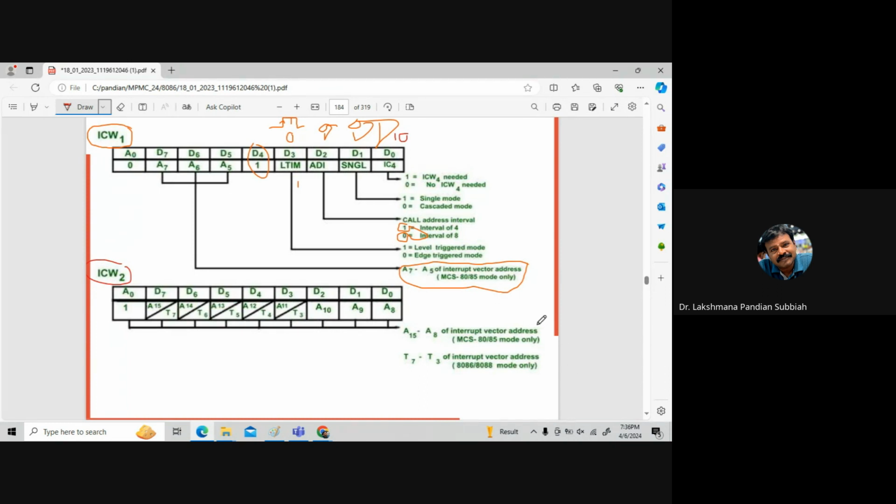So for which particular address are we going to have that interrupt vector content? Where is the interrupt vector? Where we have the corresponding address, we are going to have A15 to A8. So this is the address, and this is going to have the interrupt vector. In the interrupt vector, we have the corresponding routine address. So first routine, second routine, third routine. We have the interrupt vector.